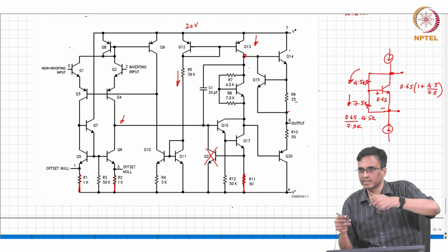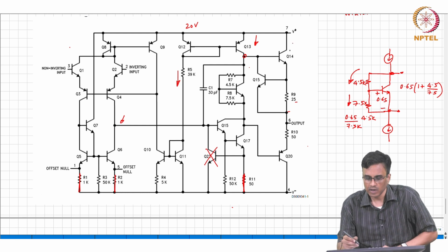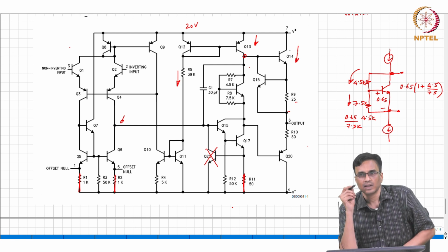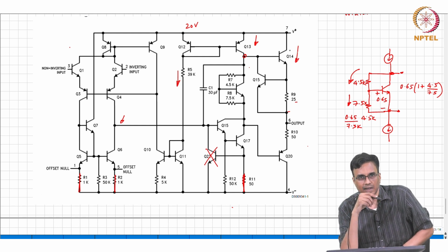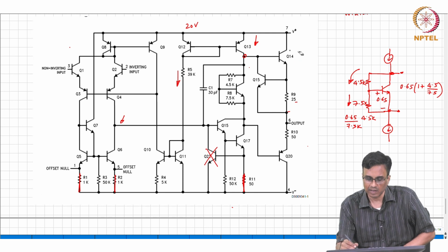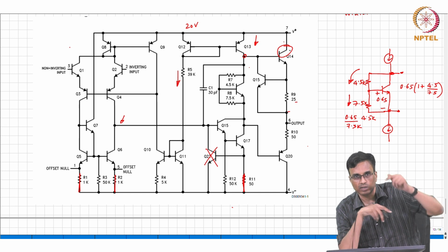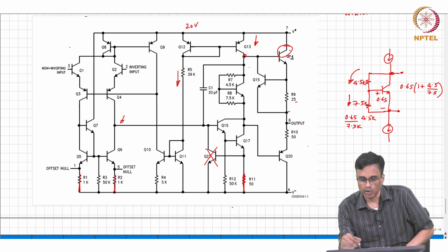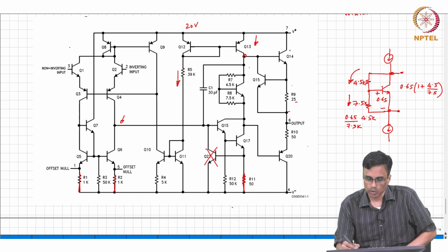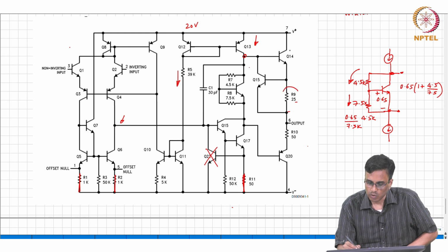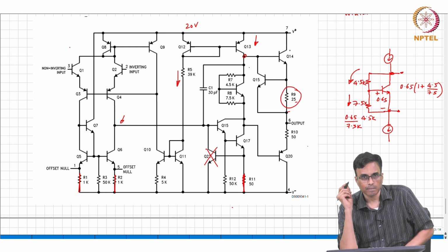A large current is trying to flow, and that is going to simply burn up the transistor, right, because most of the power is dissipated in the collector base junction, since that has the large voltage across it. So, it will simply burn up this transistor. So, what they do is, they put a small resistor, right.